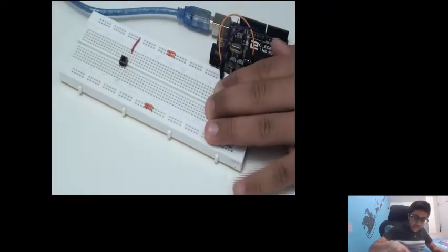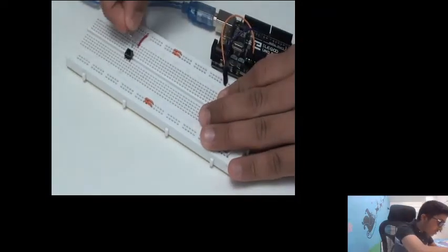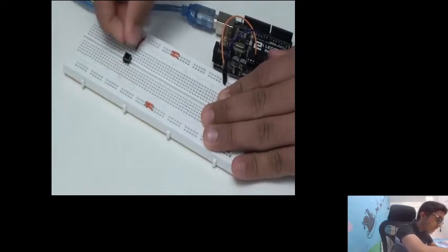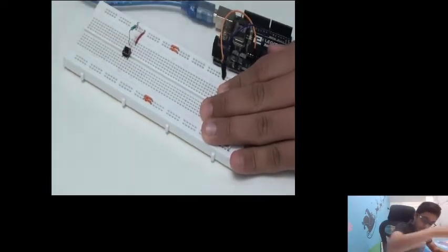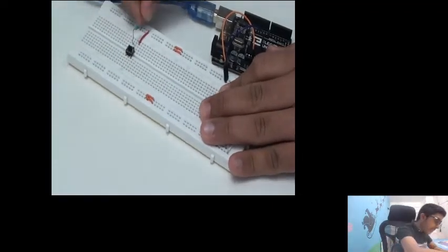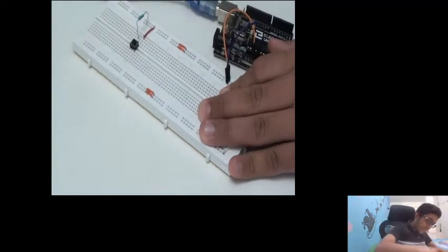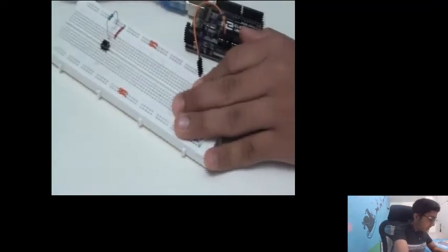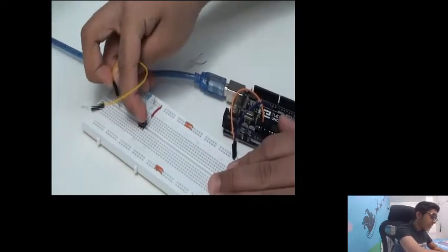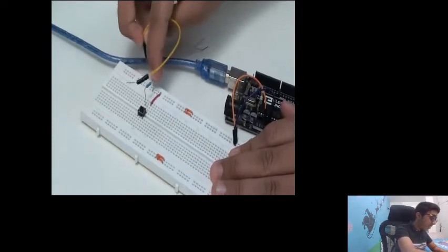And the other side of the switch is going to be connected to ground through a resistor. Always remember, through a resistor. If you directly connect it using one of these wires, it's going to create a short circuit and it's not pretty. Now here's how the thing's going to work, right? Current's going to flow from the positive terminal to the switch, and only when we press the switch, it's going to flow back to the negative terminal or the ground.